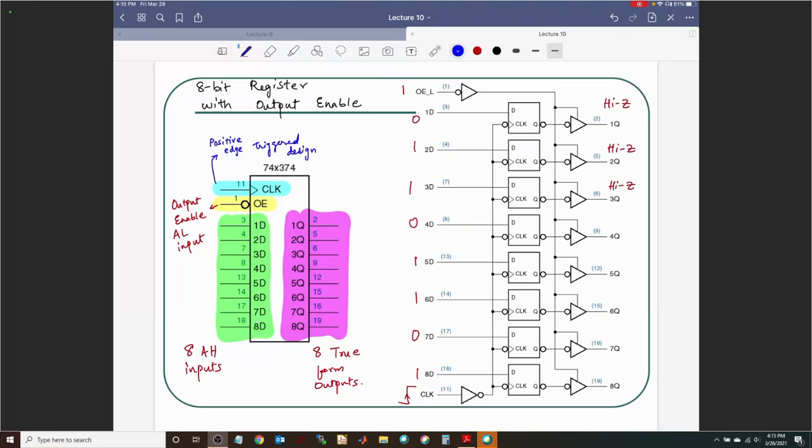Now let us try to make it 0. All right. Now I've made it 0 in blue. I've kept the same inputs 0 1 1 0 and all of that. And then there is another positive edge on the clock. Now what is going to happen? Let us see. B6. Let us see if that is right. So the way you would write it is what? 8 down to 1. So you would say 1 0 1 1 and then 0 1 1 0, right?